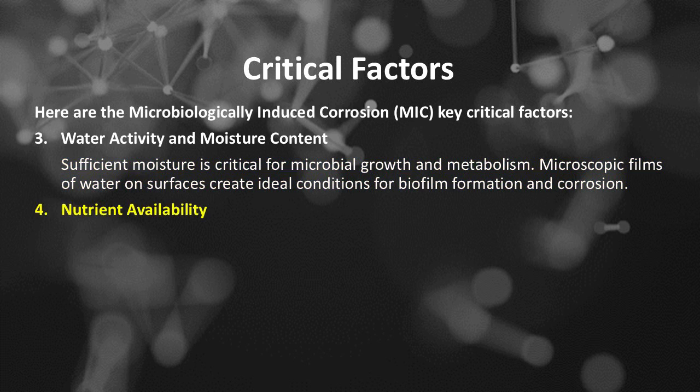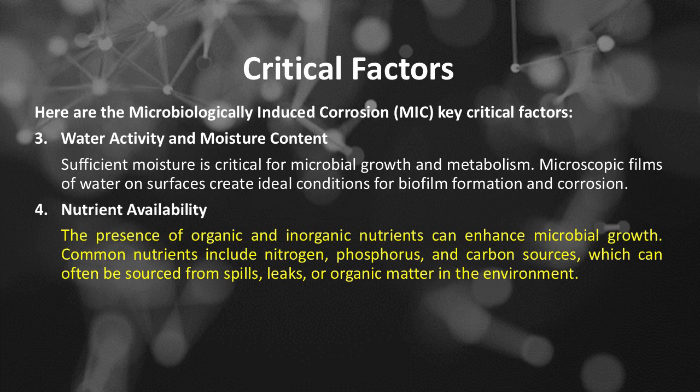Number 4 of the microbiologically induced corrosion, or MIC, key critical factors is nutrient availability. The presence of organic and inorganic nutrients can enhance microbial growth. Common nutrients include nitrogen, phosphorus, and carbon sources, which can often be sourced from spills, leaks, or organic matter in the environment.